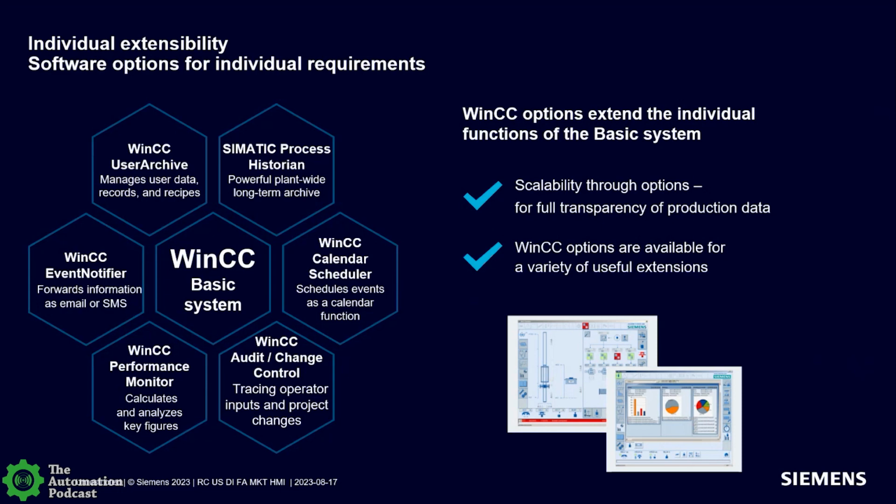It also goes more advanced where you can start building Gantt charts. And if you're monitoring equipment states, it'll help the Gantt chart build that out where you can show, hey, here's where I'm down waiting on material, or I'm down waiting on maintenance, or having problems waiting on user interfaces or whatever. So you can build a decision tree in there and have operators put information in to really help figure out where your bottlenecks are in your plant so that you can get more productivity out of your line and correct those.